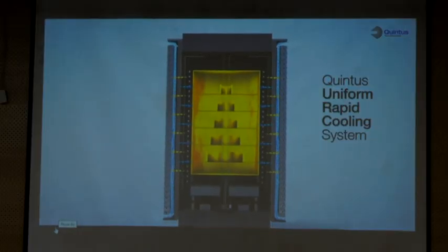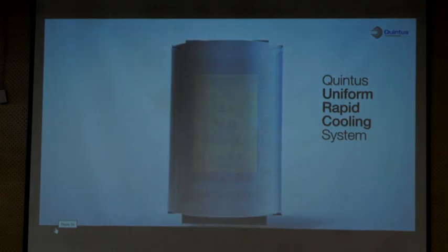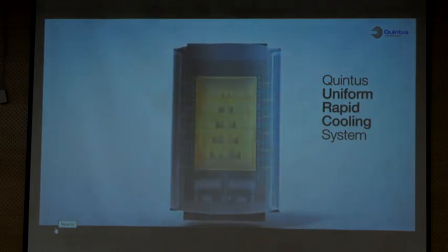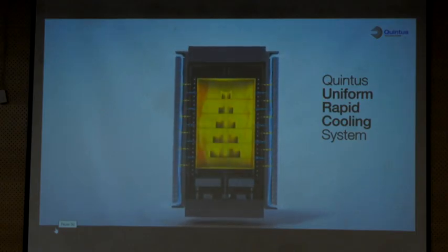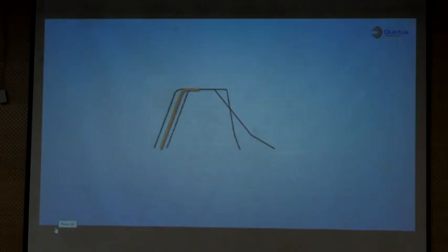At the same time, the vessel wall is cooled by water from the outside, while it is supported by the wire package to keep it safe and under control throughout the process. With this unique combination of HIP and heat treatment in one, the load only needs to be heated and cooled once. This gives significant savings in productivity and energy costs.